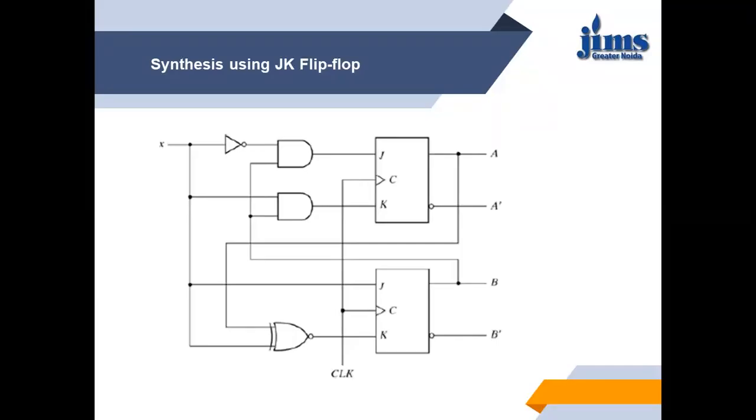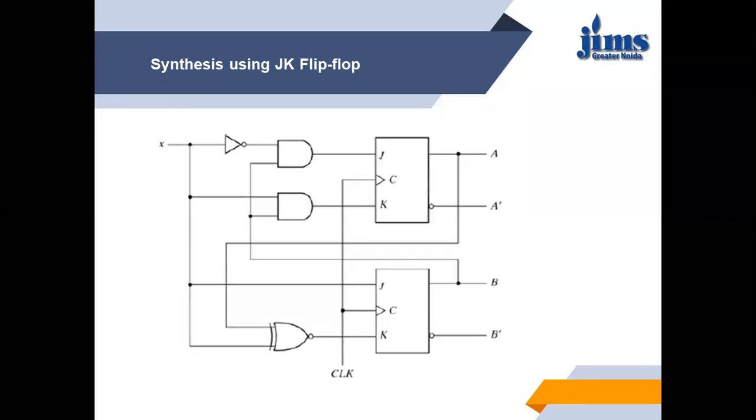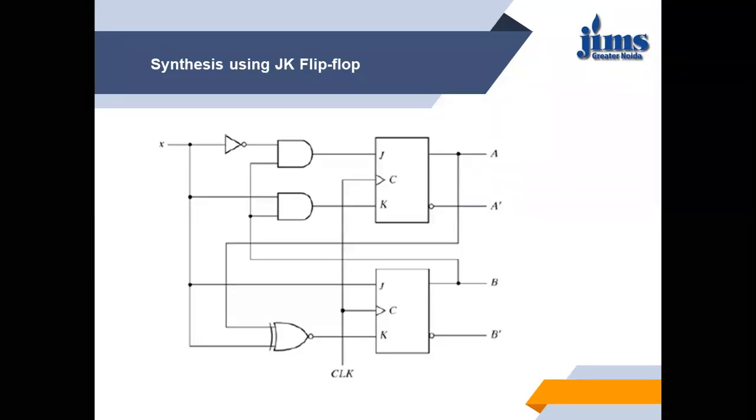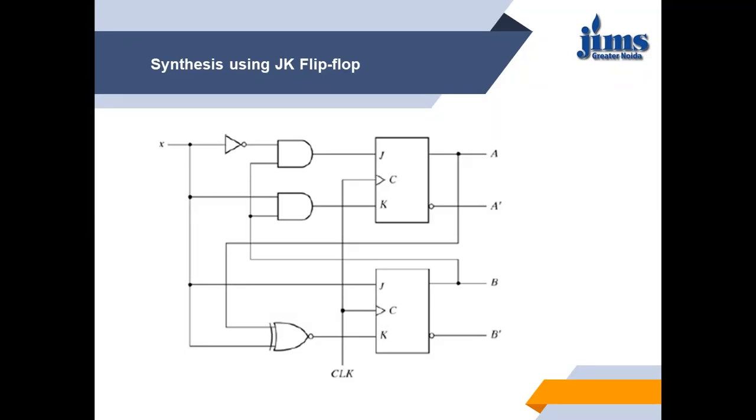So this is the way when we are given a state diagram or a state table: we find the excitation inputs with the help of the present state and next state, solve the K map for all the excitation inputs and the output, if any, and draw the circuit with the solved Boolean functions.